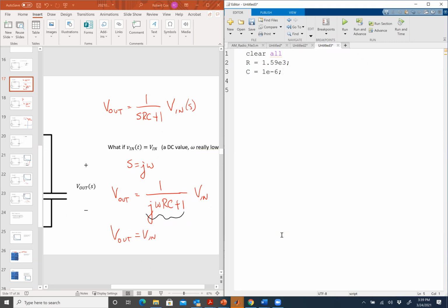So what I'm going to do is say H is equal to 1 over j times omega times R times C plus 1, like that. Now, that's not going to work. I need to give it a particular omega, right? So let's say, give me a frequency. So let's say omega was 2000, okay?